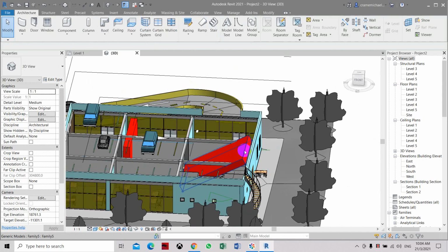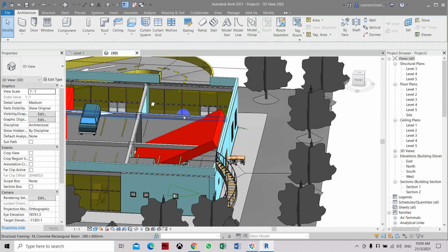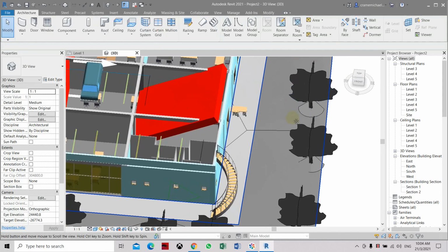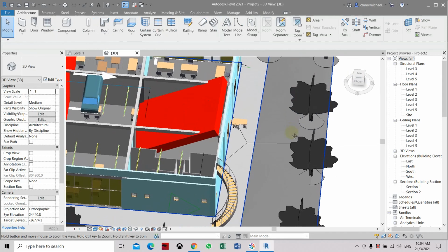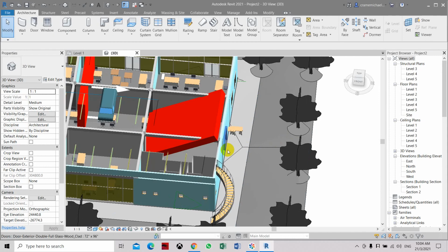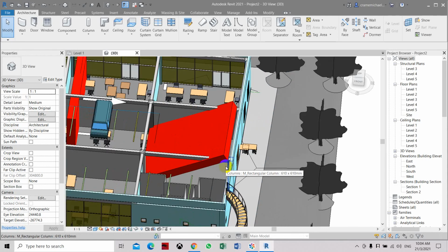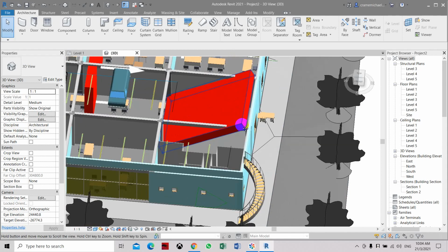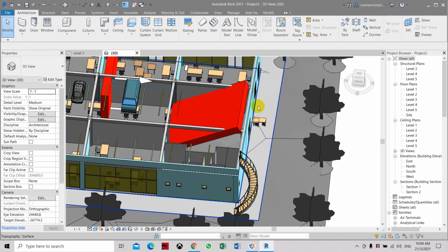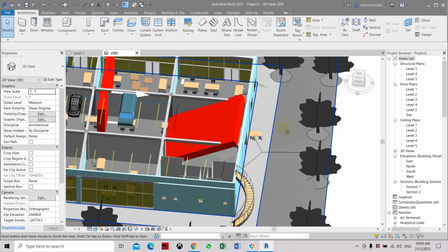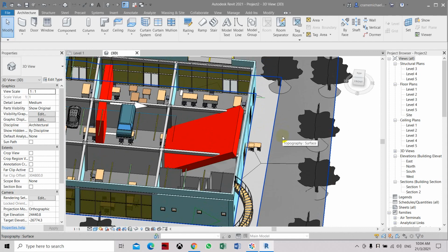You can place an inclined object with a regular shape using an adaptive model. So that is how to create an adaptive model where you can create irregular shapes following the contours or points that you want to create, using the adaptive model generic family. You can add more points, so you can have more shapes. You only used 4 points. That one you can do as an exercise to create additional points, and you may create more irregular shape objects in Revit.